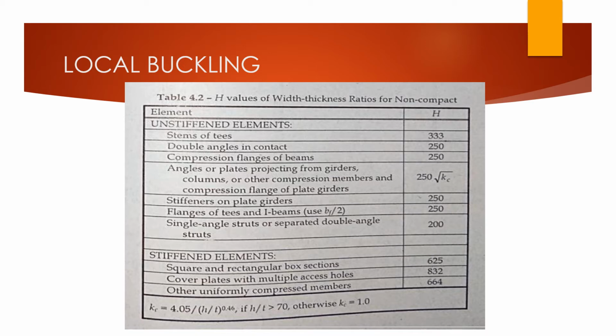The ability of plate sections to carry compressive loads without buckling is determined by the width thickness ratio B over T. If a shape is selected from NSCP tables, this ratio does not generally need to be evaluated. However, compression members constructed from structural tees, structural tubing, and plates must be checked.